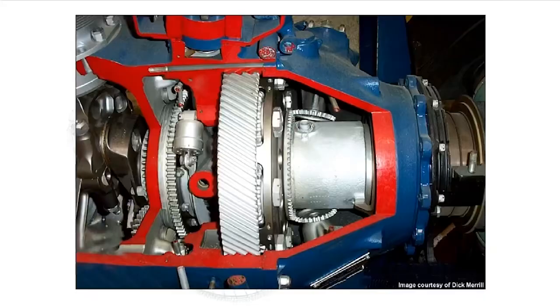So, if we have to use a large diameter propeller and yet maintain its RPM to a level that will not allow the tip speed to exceed that of the speed of sound, the propeller drive speed must be reduced to a more suitable level by a reduction gear, placed in the driveline between the engine and the propeller shaft, as is this example of a Pratt & Whitney R4360 engine, which is shown as a cutaway.